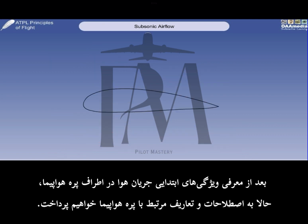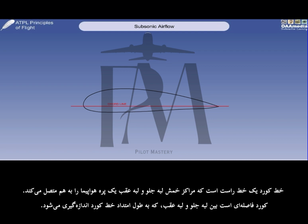Having introduced the basic characteristics of the airflow around an aerofoil, we shall now look at the terminology and definitions associated with aerofoils. The chord line is a straight line joining the centres of curvature of the leading and trailing edges of an aerofoil. The chord is the distance between the leading and trailing edges, measured along the chord line.